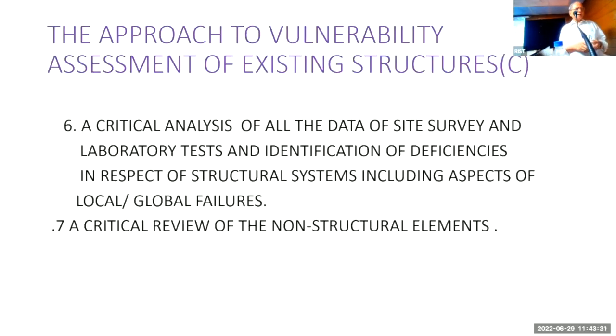Then 6th point, a critical analysis of all the data collected from site survey, then the prepared drawings or available structural drawings or the result of the test, NDT test, soil investigation. We look into all these critically and identify where is the deficiency. That is very important. Therefore, analysis of the data collected is the most important part in the process of designing the retrofit measures. So here I have written a critical review of the non-structural elements that I have told you. Why that is required, I'll come to that.